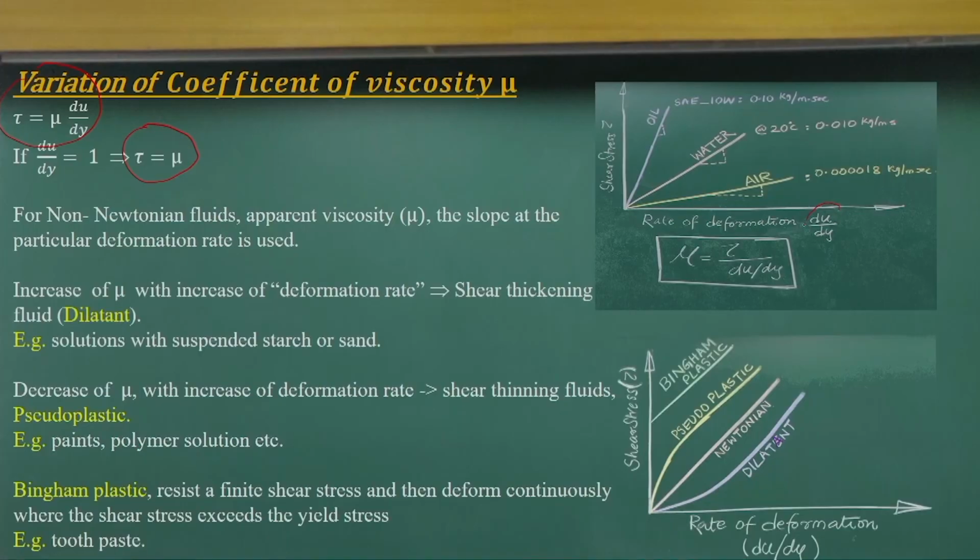If I plot the rate of deformation, the velocity gradient, against the shear stress for common fluids like air, water and oil, as you experience, whenever you drag a solid surface on water, air or oil, you need more force to drag it on an oil mass as compared to water.